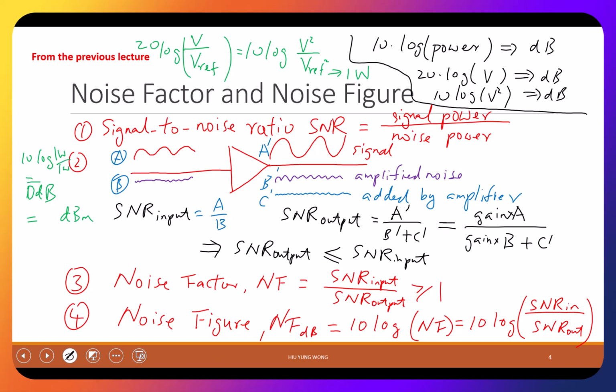That is 0 dB. This one is talking about 10 log of 1 volt divided by 1 millivolt. What is 1 volt divided by 1 millivolt? 1,000. They are both in the same units, right? So it's 1,000. What is log 1,000? 3. So how many dBm? 30 dBm.